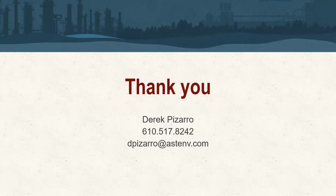The reason there is they are seeing immediate or very near-term conversion of the hexavalent chromium they're dealing with, but they've also got some PCE and TCE in the mix. And the blend they've derived for that site, that's where you need to carry out some longer-term monitoring, not just to affirm you're getting that dual treatment, but also that there are no tertiary effects.